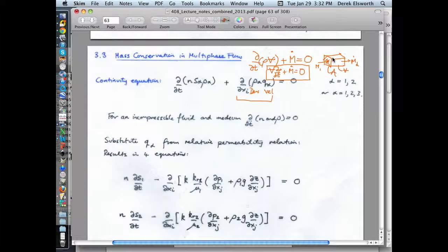And so although this control volume is constant, what could change if you have two fluids in it, you could get more water in, and that would push out more of the non-wetting fluid to be able to accommodate it. So the saturation of the water might increase, but the saturation of the non-wetting fluid in a complementary way would decrease without changing the volume of this control part.